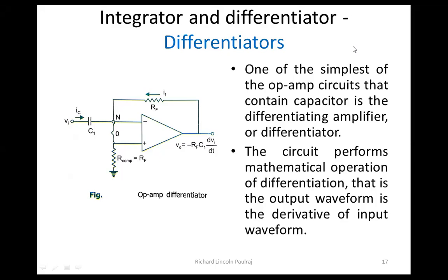So we had seen that this resistor here will actually control the effects of the bias current, right? Remember, we had IB max. IB max is about 500 nanoamps. So this resistor here will control whatever effects can be caused by the bias current. Okay, so hence this is needed. Through this resistor, whatever the currents are, slowly it is grounded. Okay, fine. So that was one important concept.